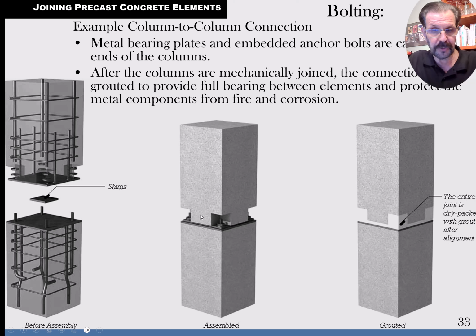After it's all bolted and torqued in place, somebody would come back with dry pack grout. Typically, they'll go and spray or mop in some concrete fortifier, basically white glue with a lot of extra water, so it's kind of a milky material that they'll spray or mop or brush in there, and about 15-20 minutes later, it's dry enough to dry clear, and then they can get a good bond with the concrete and the dry pack grout that they pack in here.